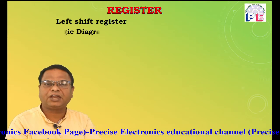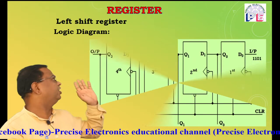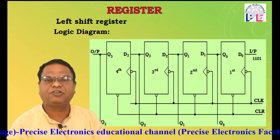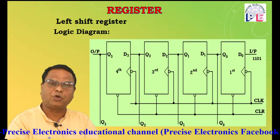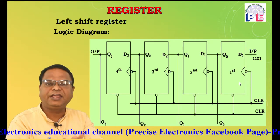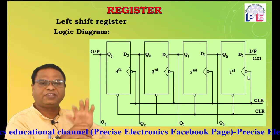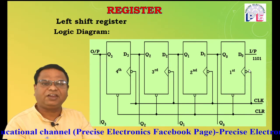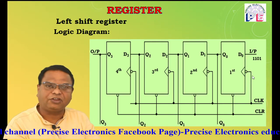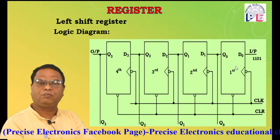Now the logic diagram of the left shift register is going to be displayed on your screen. Once again, in this shift register, 4 D flip-flops are used, and all these D flip-flops are negative edge triggered, because the bubble indicates it is negative and the triangle indicates it is edge triggered. So it is a negative edge triggered D flip-flop.